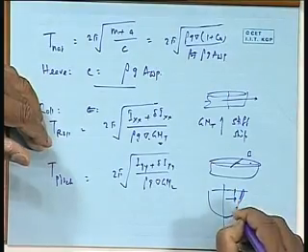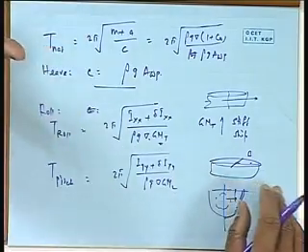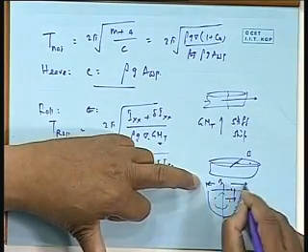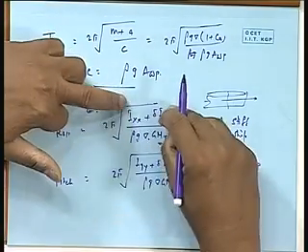You can make it out, because obviously more weight is on the shell, where more side frames are there. So it is more like a hollow cylinder, shifted a little outside, but not fully hollow, because quite some weights are also scattered inside. So it is in between, and people find that it is about 30 to 35% of breadth. If it is exactly half, it will be 25%, because the breadth is the full thing. Remember, this is my B. If it is halfway of B, it will be 25%. It is a little more than that. So you can estimate that.